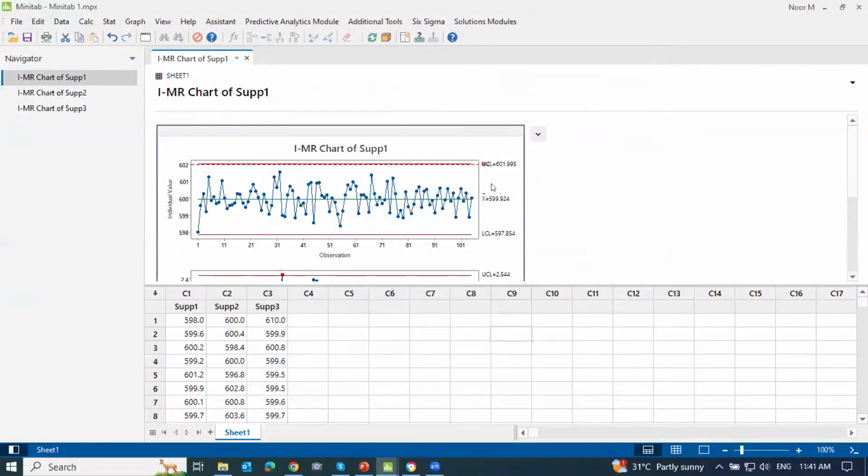So you can add a reference line into this IMR chart or other control charts, but just to highlight, since the IMR chart is individual, it is okay to add a reference such as a spec limit. But if your control chart is a group control chart, something like the Xbar-R chart, it will be grouped. It's not so good to add the spec limit, because the point is not an individual point. It comes from one group in this case.